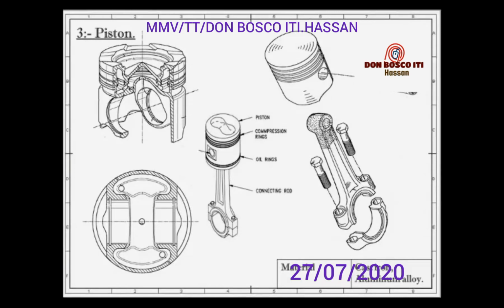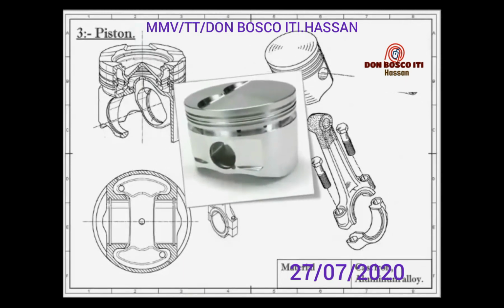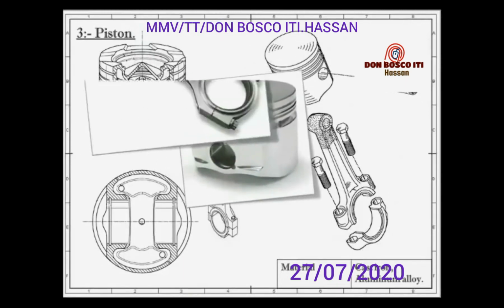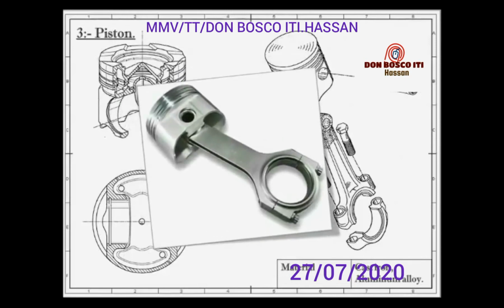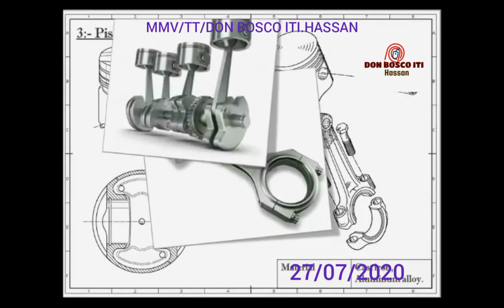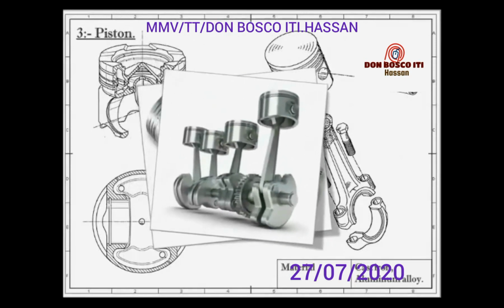The other function of the piston is to give a tight seal to the cylinder bore and slide freely inside the cylinder. Piston should be light and sufficiently strong to handle the gas pressure generated by combustion of fuel. So the piston is made of aluminum alloy and sometimes of cast iron. Because light alloy pistons expand more than cast iron, they need more clearance to the bore.